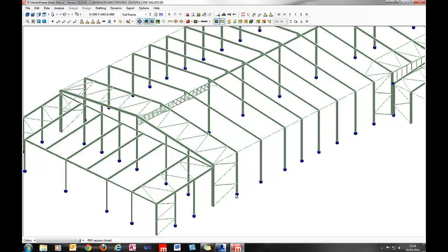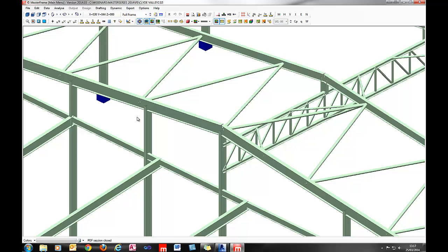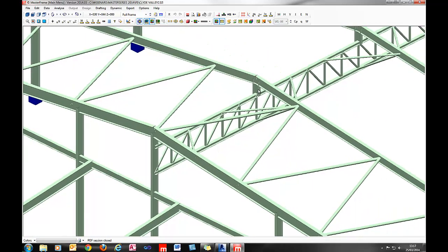Interestingly, the IFC format or standard in itself does have the ability to hold structural analysis lines as opposed to physical objects or physical members. However, many people export an IFC, but it is not compulsory for other applications to provide that information, and indeed many other applications wouldn't even have that structural analysis lines type of information.